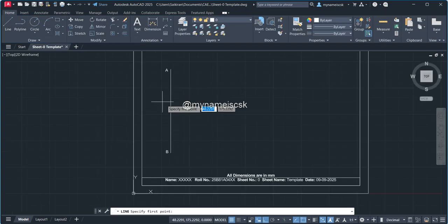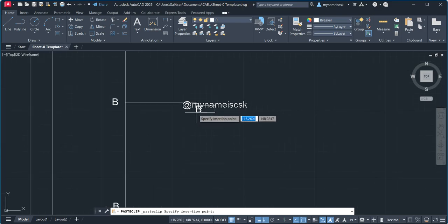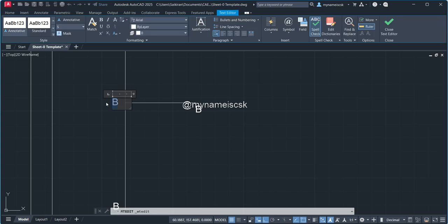Then click on line. You have to find the center of the line. Then from the midpoint, I will take a distance of 50. In the problem they mentioned CF distance is 50. So I have to select the CF distance and again copy this, Ctrl C and Ctrl V. Mark this at the bottom. Rename this as C and rename this as F.